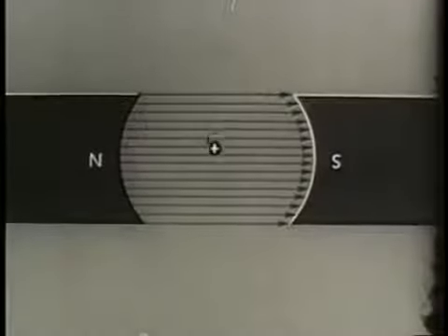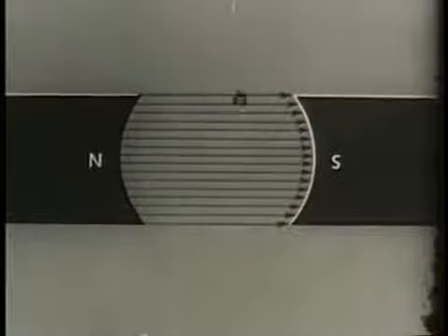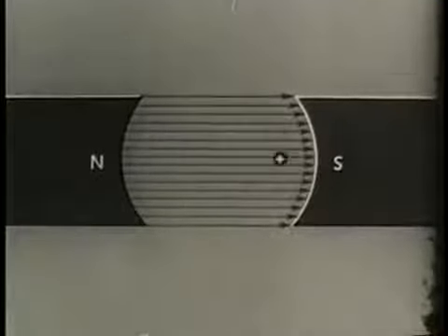This formula assumes conductor motion in a straight line, that is to say, cutting the same number of lines for each increment of its motion. But the conductor in an actual machine is not moving in a straight line, but rotating. When the conductor moves in a rotary path, the number of lines cut varies depending on the position of the conductor.